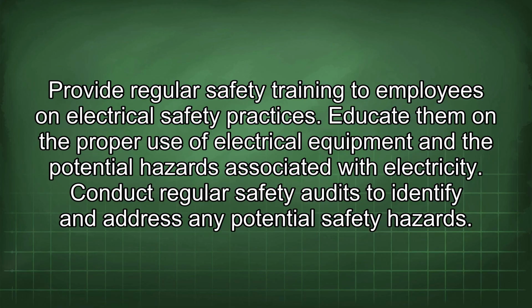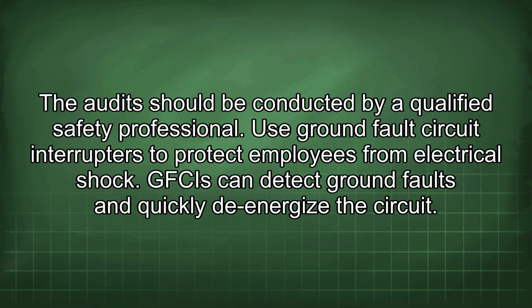Conduct regular safety audits to identify and address any potential safety hazards. The audit should be conducted by a qualified safety professional. Use ground fault circuit interrupters to protect employees from electrical shock. GFCIs can detect ground faults and quickly de-energize the circuit.